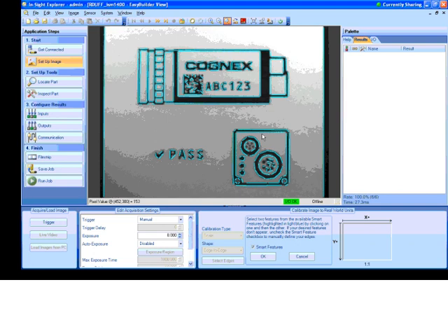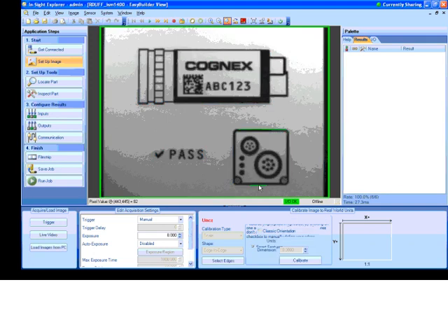So I'm going to measure from this line to this line, because I know this is a micro, and I know it's 30 millimeters. I'm already set for millimeters, so I'm going to put in 30 here, and say calibrate. Boom, done. Scale calibration. We could also do grid calibration. I could put a target here in my field of view and set that up. That was part of an earlier class, so right now I just wanted to do that much so that all of our values will come up as millimeters.